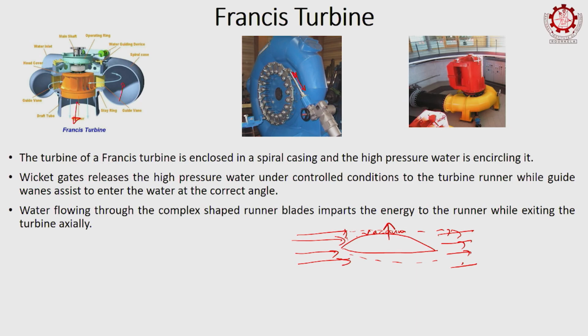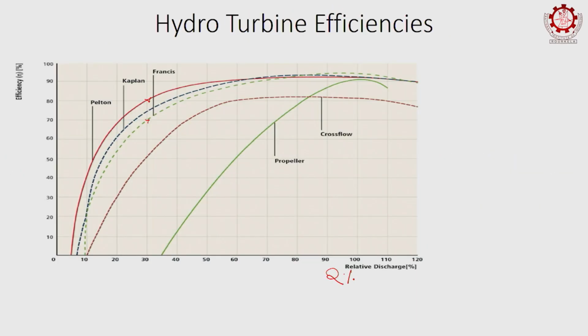That way we can overcome this problem of part load poor efficiency of Francis turbines, right, by employing, if you have a site where you want to have a 1 megawatt or 1000 kilowatt plant, where a Francis turbine is the suitable machine, but you have a part load deficit, a lot of time to operate at part load.